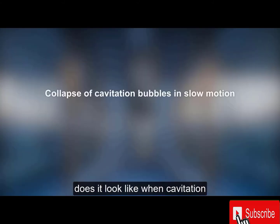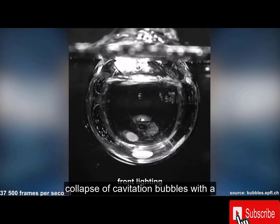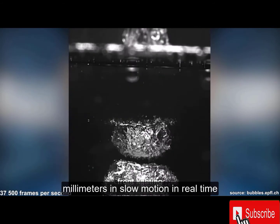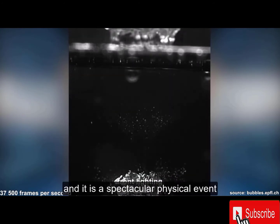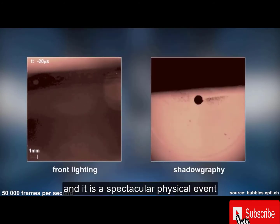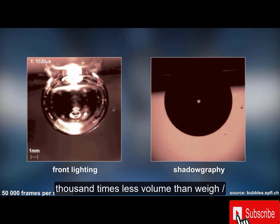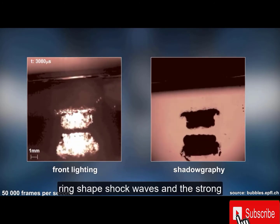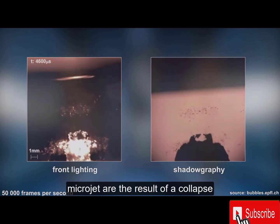But what does it look like when cavitation bubbles are formed and collapse in detail? We can see the formation and the collapse of cavitation bubbles with a diameter of approximately 9 mm in slow motion. In real time, this process takes about 4 milliseconds, and it is a spectacular physical event. Because liquid water occupies many thousand times less volume than vapor, the bubble implodes. It first assumes a ring shape. Shock waves and a strong microjet are the result of a collapse.